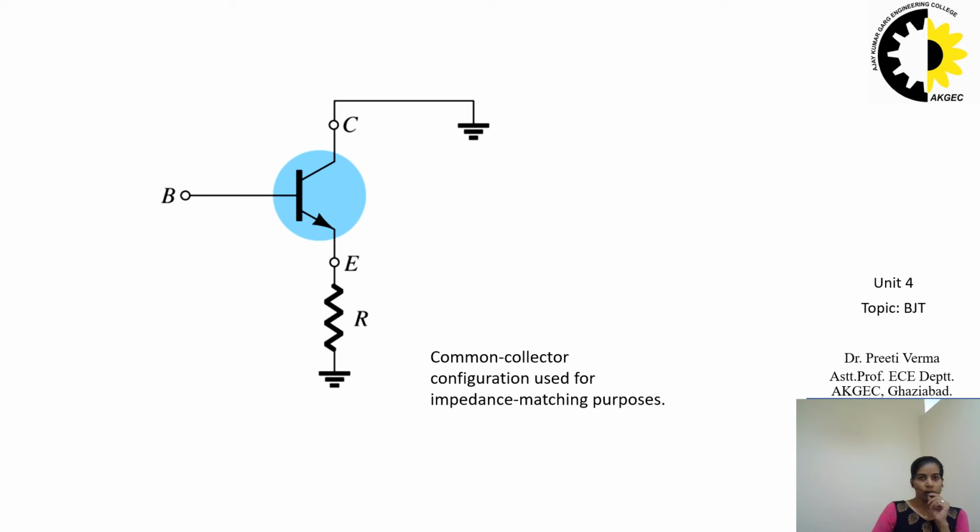The horizontal voltage axis for the common collector configuration is obtained by simply changing the sign of the collector to emitter voltage of the common emitter characteristics. Finally, there is an almost unnoticeable change in the vertical scale of IC of the common emitter characteristics if IC is replaced by IE for the common collector characteristics, since alpha is nearly equal to 1.